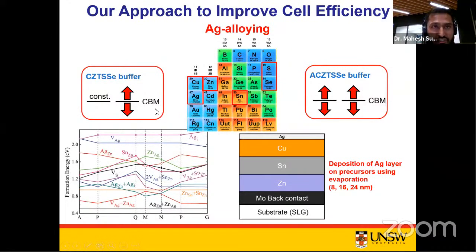The third one is passivation in the junction region using wider bandgap materials, again the same as zinc oxysulfide, cadmium zinc sulfide, zinc tin oxide, or copper aluminum oxide. And the fourth one is the introduction of alkali metals such as sodium, potassium, or lithium occupying these copper vacancy defect sites. Among these approaches, the partial substitution of the copper by the zinc side.